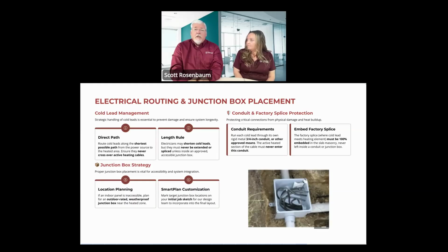Yeah, and the National Electric Code says that you need 3/4 inch rigid metal conduit to go from that. It needs to be butted into the heated area because that cable has to be protected. That black cable should never see the light of day. It's not rated to run in dirt. It needs to be in conduit.